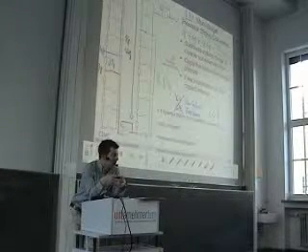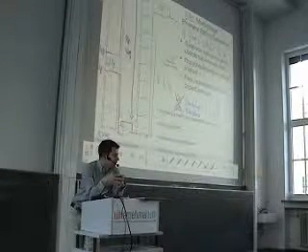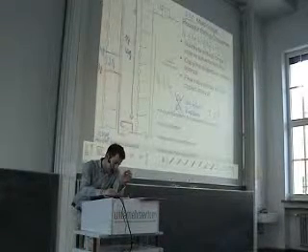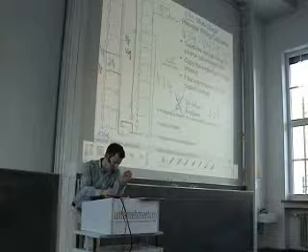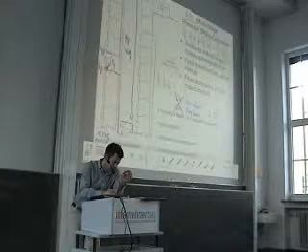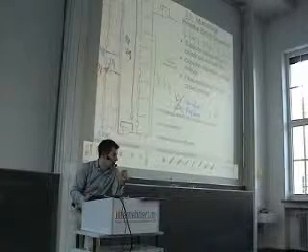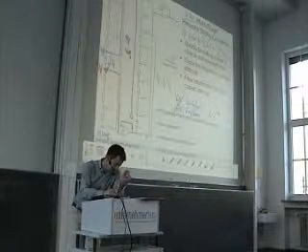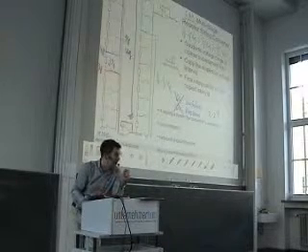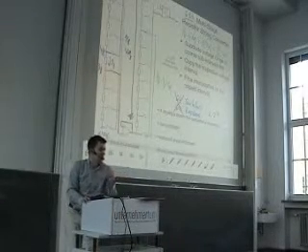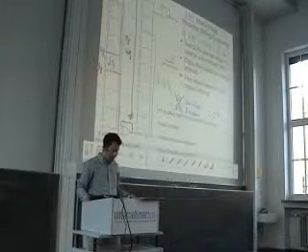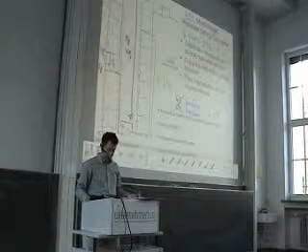And of course, these buffers need a good matching in order to achieve that we really have here the voltage or a copy of the voltage difference in between the resistors here. So this voltage difference is here copied to these 2 nodes, and of course therefore we need a good matching to have a good copy of this one. Okay.